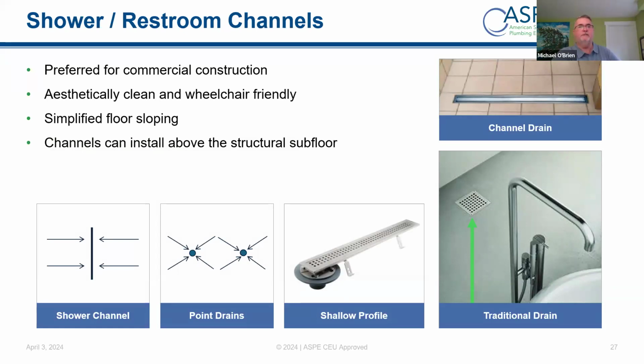Moving along, shower restroom channels. Really, really common these days to go with a channel drain, or what we would call a shower channel. It makes for a much simpler slope of the floor to the drain, and is quite common now in healthcare facilities, because people in walkers or wheelchairs don't have to deal with that multiple slope of using a point drain.